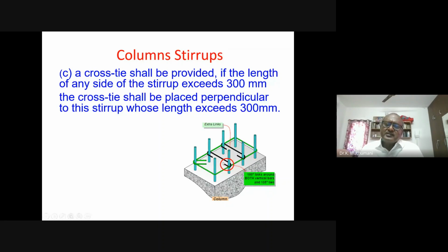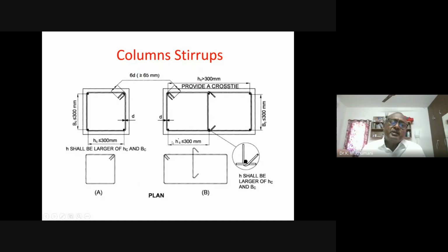So you provide in between some stirrups like this. This is what is called confinement. This is a little science only, but there is no design calculation. You cannot ask me how to compute this shear stirrup that is shown in the block. If it is more than 300 mm, you provide one. That is the only way that I can explain, because that is how confinement is.